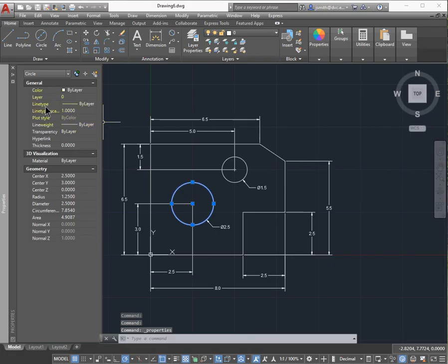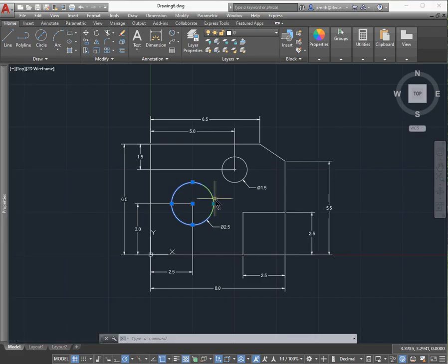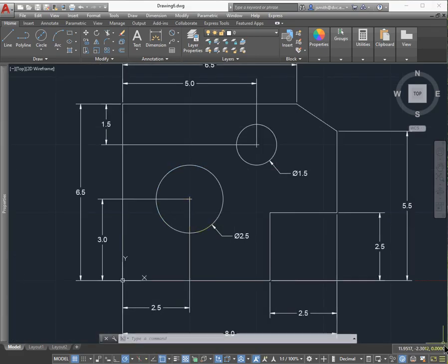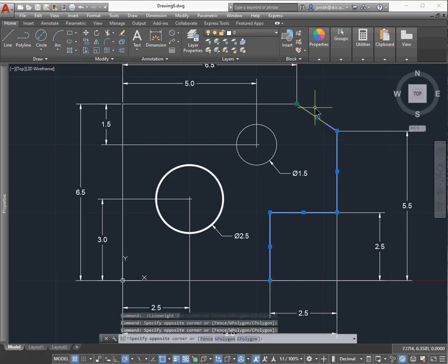So you want to put it, this is in millimeters, we're going to do it at 0.5, all right? You're going to have to try this, but right now nothing has happened, right? So if you come down to the right, make sure that the line weight tab is selected, and then you turn it on. This is the line. On the bar below, it's these 3 horizontal lines, and you select it, and that turns it on.